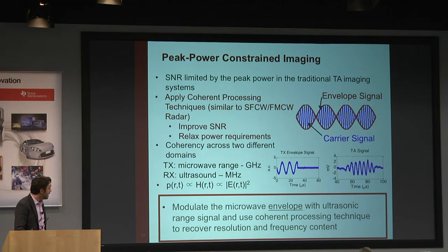There's a couple of problems here. So you improve SNR, but the problem is, unlike radar, here we're going in with microwave, which is about gigahertz, and we're coming out with ultrasound, which is megahertz. So coherently processing these two is not obvious.